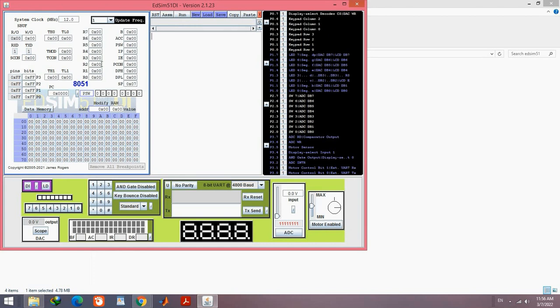All of these register contents can be manually changed. For example, if you want to change the content of this register, you can enter it here. 0x for hexadecimal base numbers, and for example FF. So I initialize register 0 by this number. But the ones that are displayed in gray color cannot be changed.